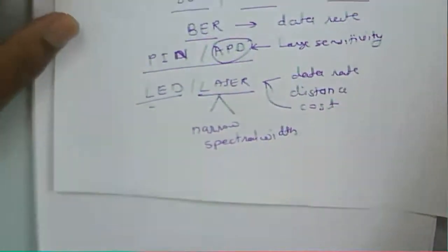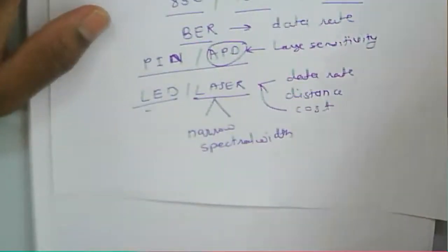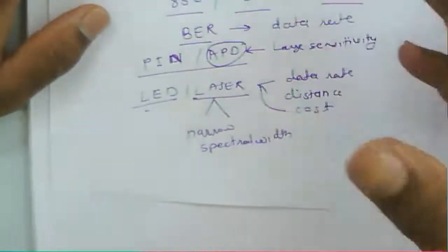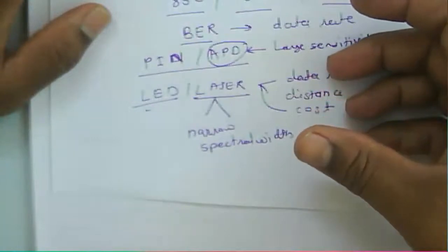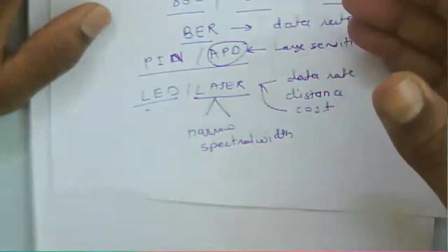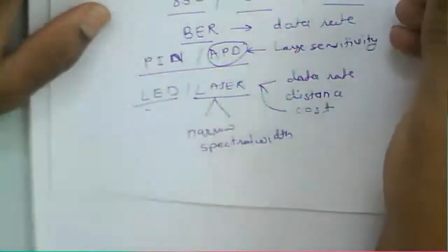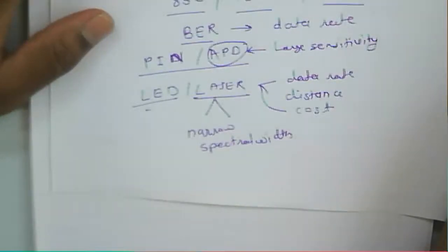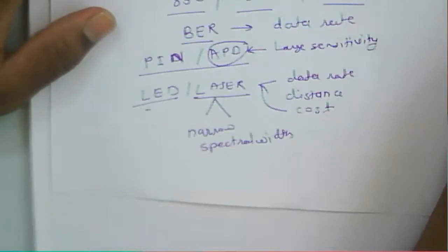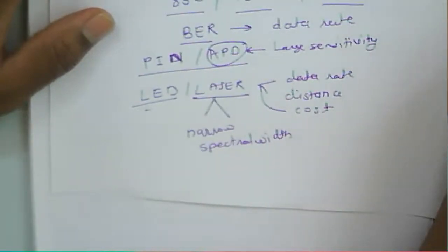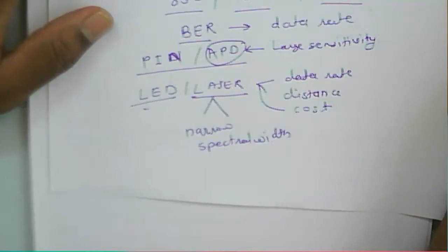That is about the system requirement, and for it we need to see what the optical fiber will be, whether single mode or multimode, and whether the multimode fiber will be step index or graded index. Choosing that fiber depends upon the type of source we are using and the dispersion tolerated by the optical fiber. Generally, with a light emitting diode we can use a multimode optical fiber, and we need to know the core and cladding difference. So that's all.